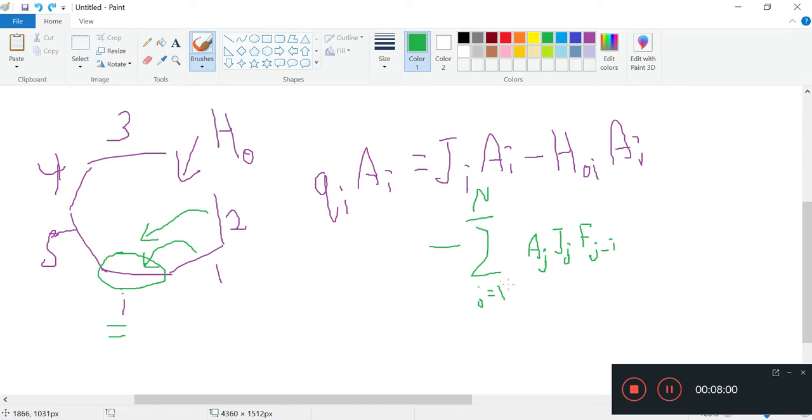Okay, so what is this saying? It is saying the total heat coming from, let's say, surface J to I, or surface 1, 2, 3, 4, 5, whatever, to I, it is this much. This is the total heat coming off the surface, and this is the fraction of heat that goes from this surface J to surface I, right?